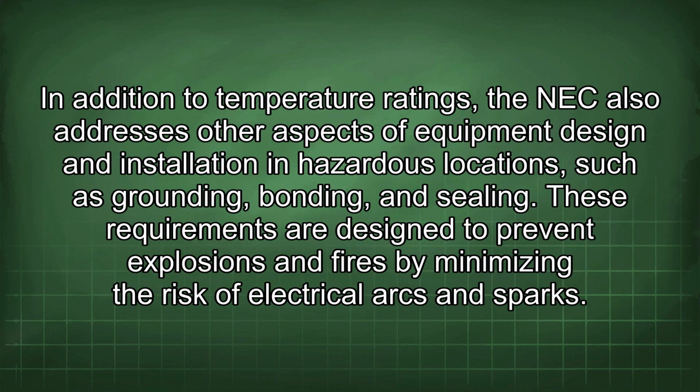In addition to temperature ratings, the NEC also addresses other aspects of equipment design and installation in hazardous locations, such as grounding, bonding, and sealing. These requirements are designed to prevent explosions and fires by minimizing the risk of electrical arcs and sparks.